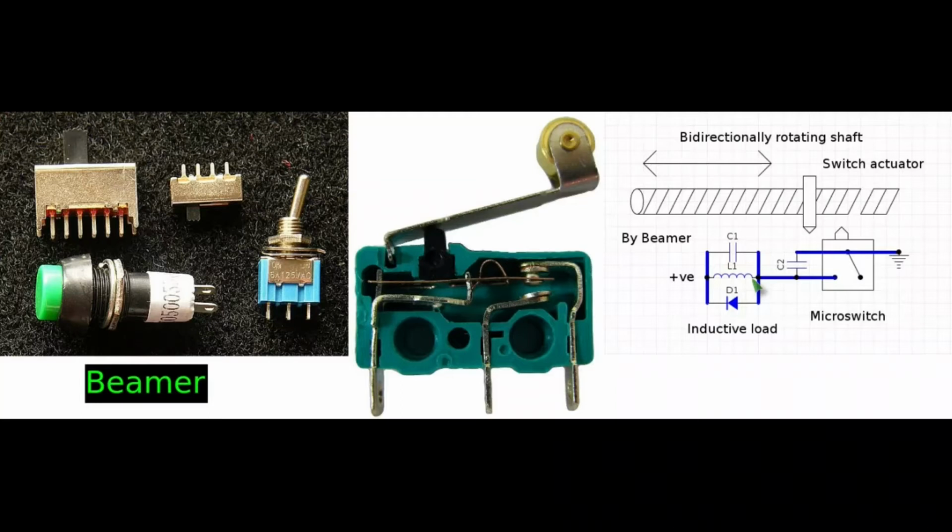I kind of knew, I felt that it was something to do with the way this micro switch was being physically operated, maybe operated too slowly, or had some form of resonance in this mechanical shaft, and in some way was causing an oscillation on this point here that was stressing this inductor, the motor or the solenoid. And I came to a solution, and it solved the problem.